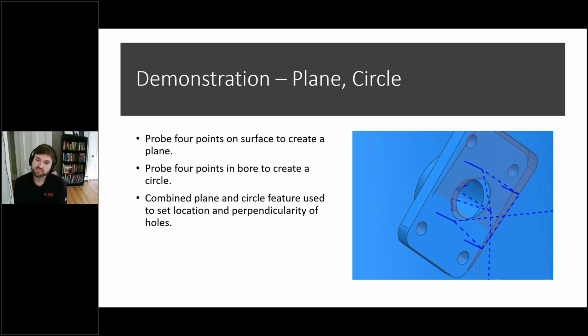And then we can also probe the inside of that bore and create a circle and use these two local orients together to position that hole pattern so that they're both perpendicular to the surface and relative to the center of that bore simultaneously.